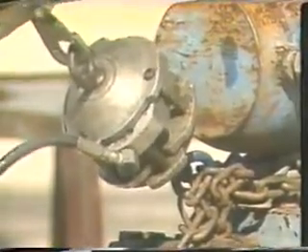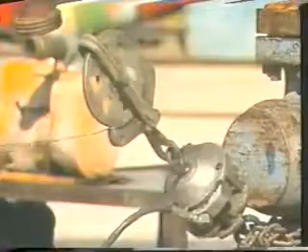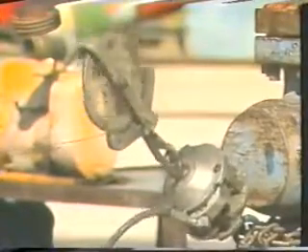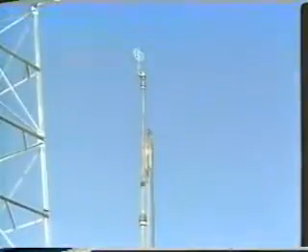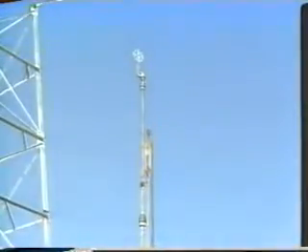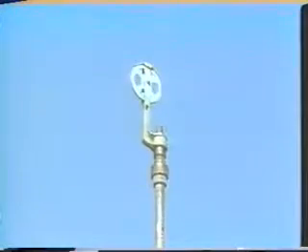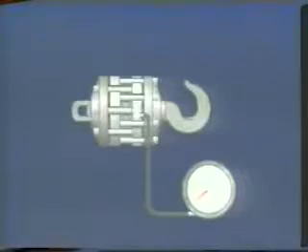To the other end of the load cell is attached a sheave, which is called a hay pulley. The wire line from the wireline unit is strung through the hay pulley and continues up the side of the lubricator to the sheave on the stuffing box and on through the stuffing box to the wireline socket of the tool string. Inside the load cell is a fluid-filled diaphragm.